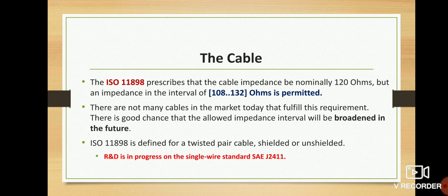But as I said, you can do some R&D on 120 ohm resistance to 130 ohm resistance. If you go to 150 or 160 ohm resistance, you will not get a proper signal. For that, again, you have to change some other parameters, so one parameter will impact another parameter. In this way, you have to do some R&D if you are really interested. Yes, of course, some R&D fellows are doing that, but this is the outcome of that. So maybe in future it may be broadened.